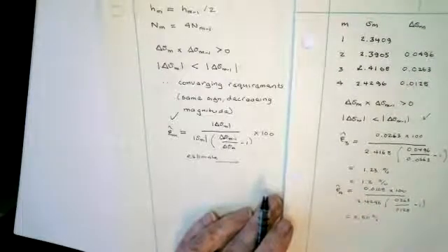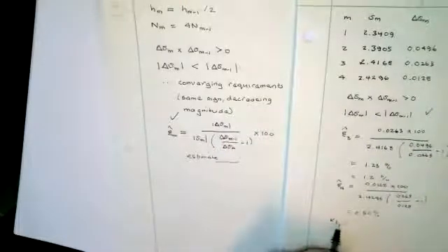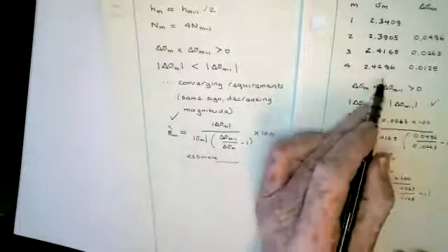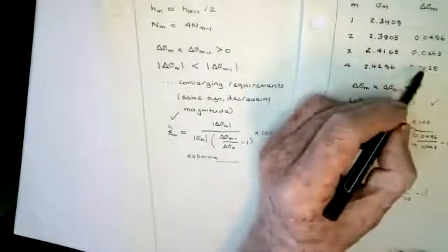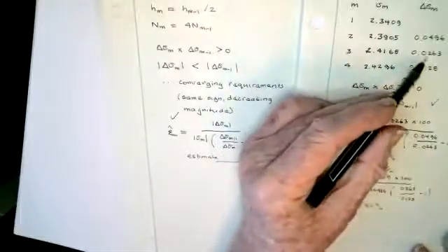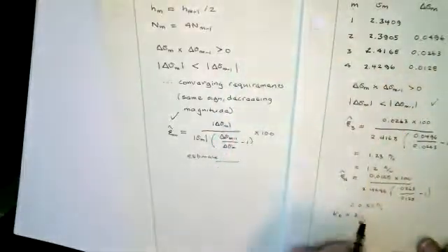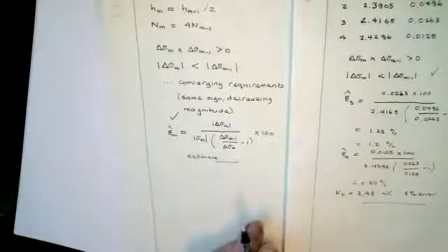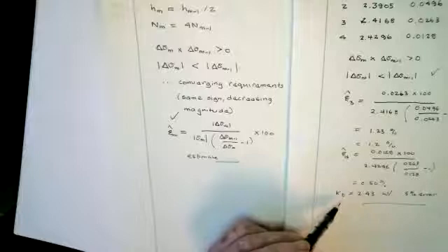So from this analysis, what we would say then is that KT, which is sigma m, we'd say 2.43. We have more decimal places here for taking the differences, and we got 3 figures in the differences, which is good. That's what we want. But obviously, at the end of the day, we'd say 2.43 with 0.5% error. And in finite element analysis, that's a good result. I'll discuss that more next time, but what levels we need to get to.